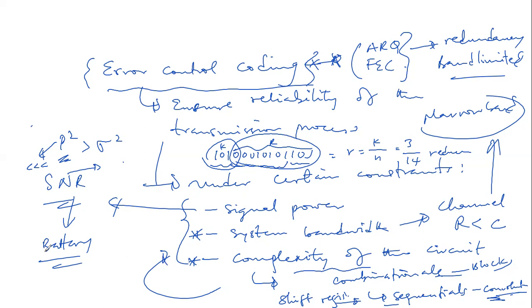But an alternative for band limited channels is to use the Trellis codes, which we are going to talk about. Because they do not require the sacrifice of either data rate or bandwidth, they are more robust. So when we talk about convolutional codes, we are going to talk about the Trellis codes, because we use them for maximum likelihood decoding. Only that the circuitry is quite complex.